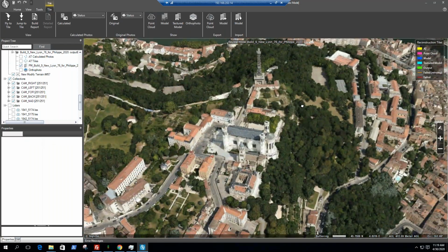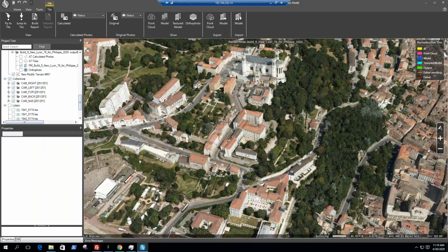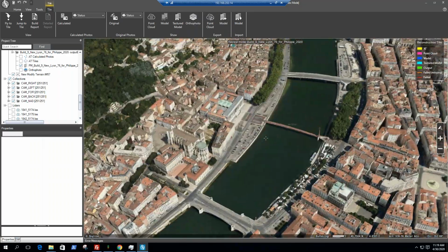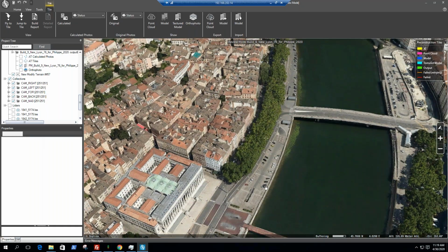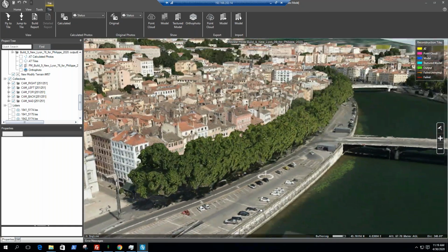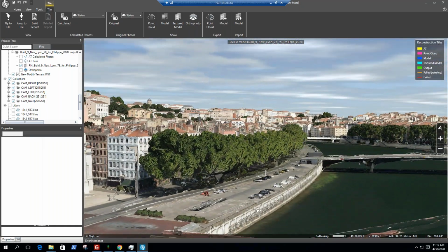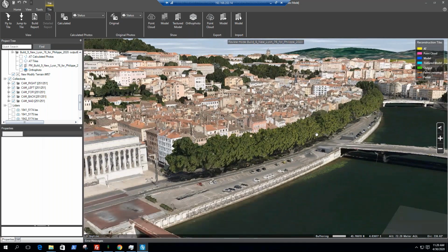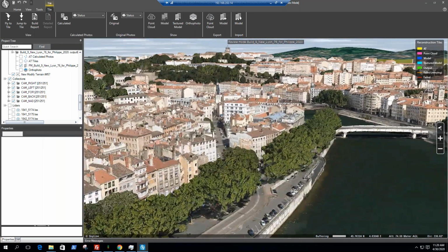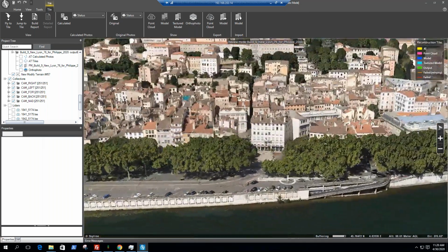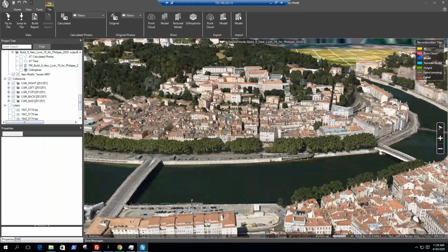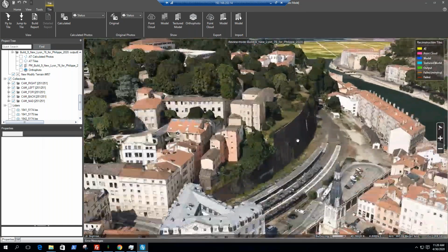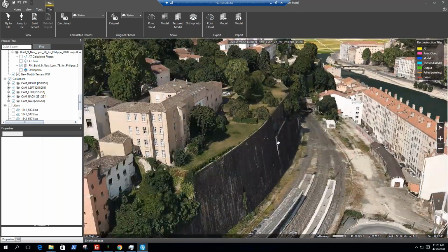But it produced slightly better quality, if only for the fact that the LiDAR was denser and the image overlap was denser. So you could see areas that have tree vegetation because of the density of the LiDAR actually completely correlate the data below the trees and the vegetation. And you can see also the level of detail on vertical features because of the density of the LiDAR gets contributed a lot.